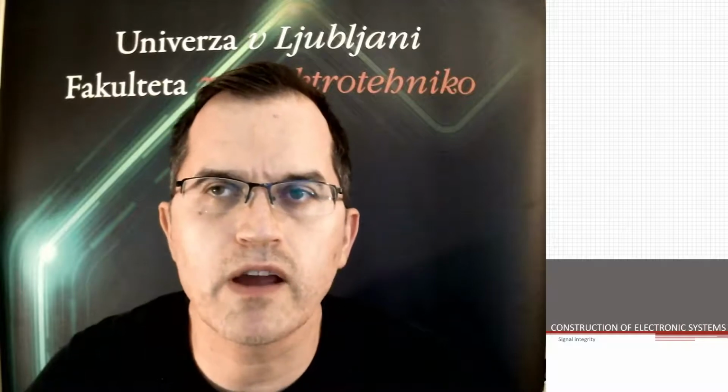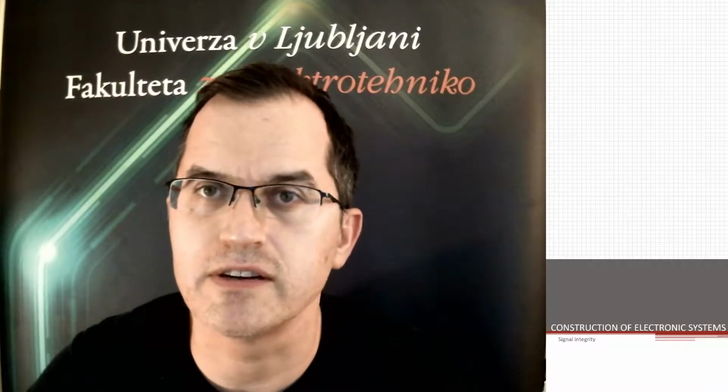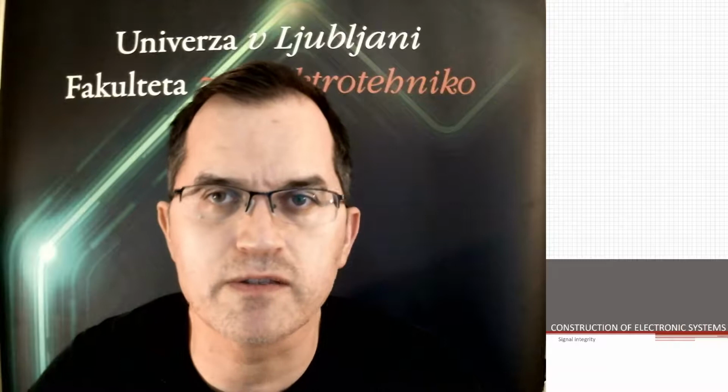Hi, today we will talk about signal integrity, which is a continuation of the previous lecture on ground planes, where we had these ground planes acting as a reference plane for the tracks above or below them. And we said that especially for high frequency signals on these lines, on these tracks, we have to know the impedance of the tracks, and this impedance should be well controlled. So why is that so? And the answer is signal integrity.